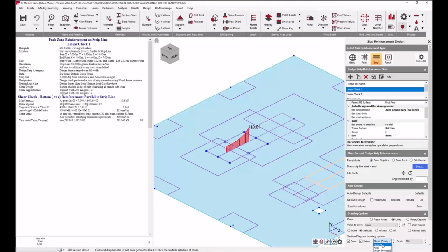Yeah, perfect. So we have a new feature here whereby you can see, and Patrick showed this, both the moment, the axial force and the shear force, whereas previously that only showed you the moment. What we're seeing here, obviously, we can see the value of moment now changes in terms of its sign from tension on the top of the slab to tension on the bottom of the slab as it comes away from the supporting planted column, as you would expect. The shear check will travel all the way along this strip and in accordance with the offsets that have been specified. So that's the moment. So when we're looking at the shear, it will obviously, in accordance with the offsets, start, and it will then change side of the slab.